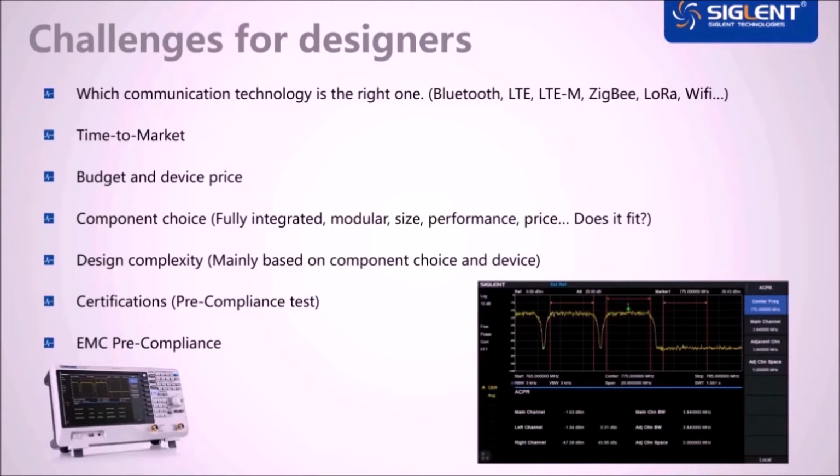Of course, the topic EMC should also not be underestimated, especially when you use a device with a high-frequency DC-DC converter to be particularly efficient and also have antennas in your device. At this point, these antennas are a perfect way for the distortions to leave your device.